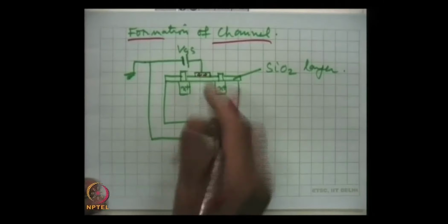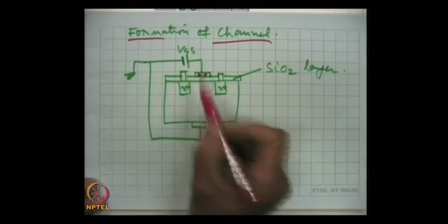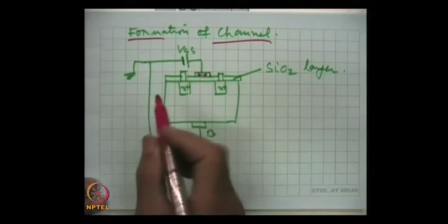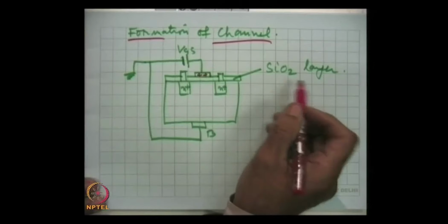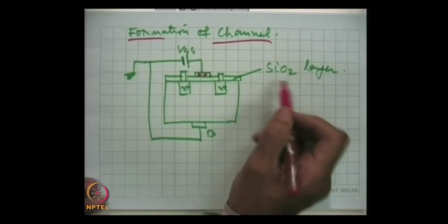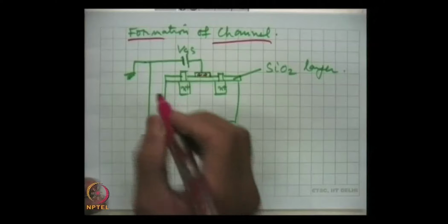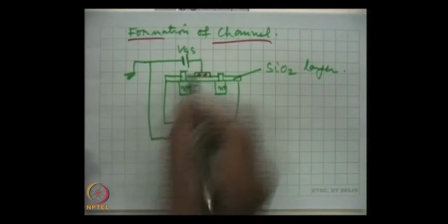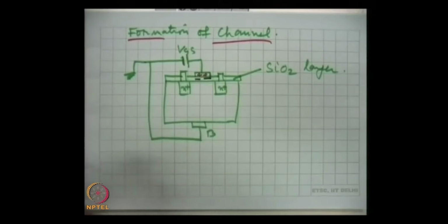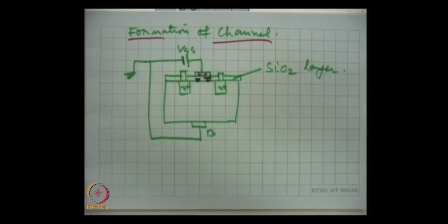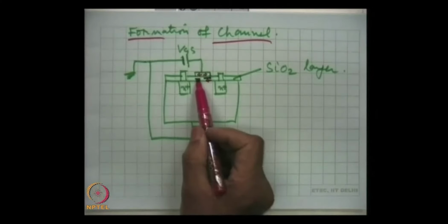So this is the voltage which is established between this semiconductor and this gate electrode. This will polarize SiO2, the silicon dioxide dielectric layer. So, here negative and positive charges, they will be on the two sides of the insulating layer. So, what will this positive charge do?